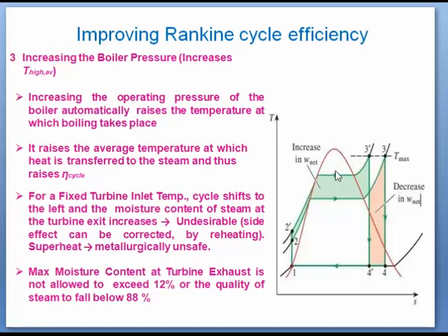Once we are increasing the boiler pressure, this superheating ends at point 3 dash, and from that 3 dash steam expands in the turbine, and the final state of the exhausted steam from the turbine is 4 dash, which has now shifted towards the left, or you can say this 4 dash condition lies in a more wet zone in comparison with the state condition at 4.